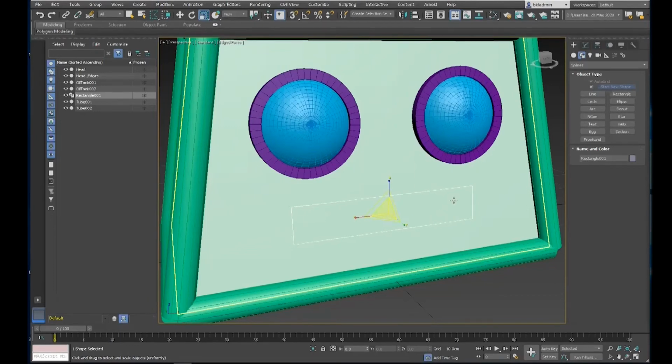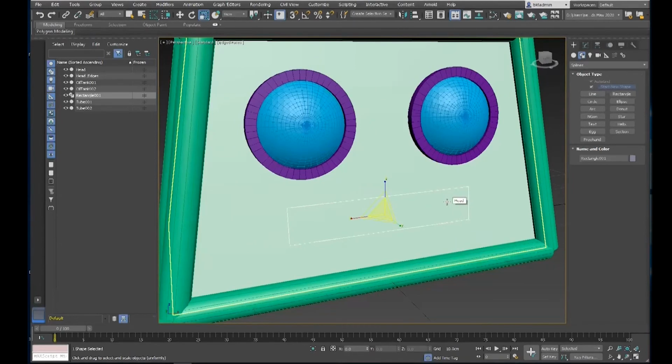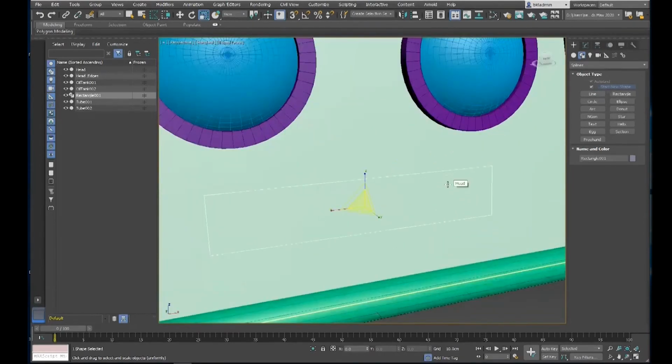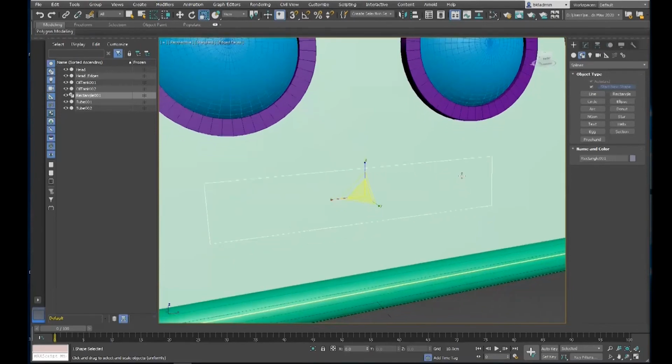So to turn this on and off, there's this hotkey. It's simply press J. So J, as Jake, is turning this little bracket on and off, and actually it's much more readable. So now you have only the line that you created, so you have no kind of ghosting lines. It's a little bit misleading when you see that selection bracket around rectangular surfaces.